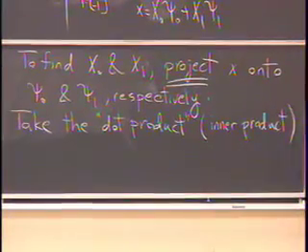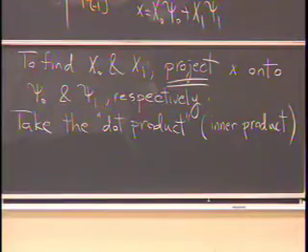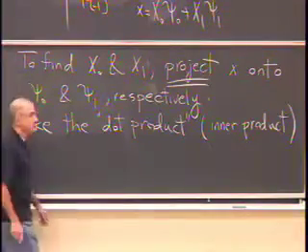It's defined for a more general class of signals. Dot product you know as something that applies to real-valued vectors. We are no longer limited to real-valued vectors. For this particular example, everything is real-valued. X is real-valued, C0 and C1 are real-valued. But you can easily see if I change the periodicity of the signal to 3, then C0 and C1 will no longer be real-valued. Well, this one will always be all ones. But these other ones, C1 and C2, will no longer be real-valued.